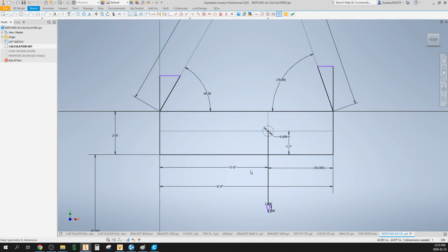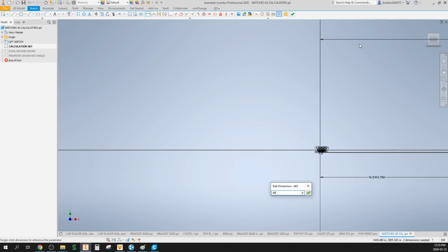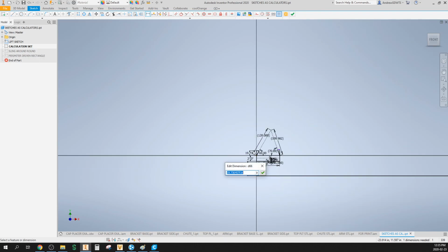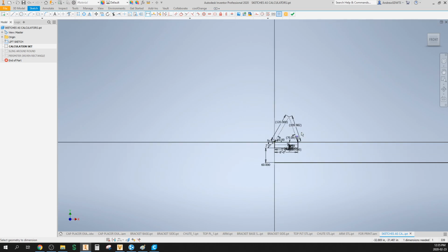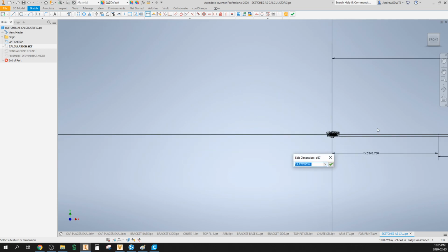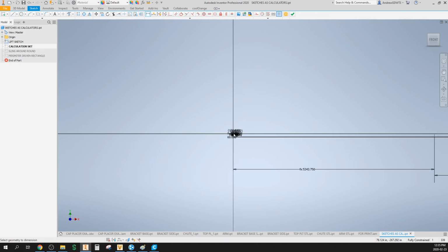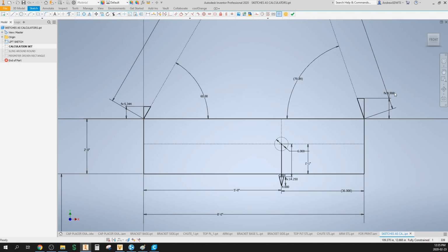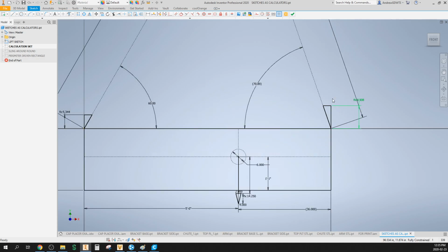To help me visualize this, I'll throw those weights into this diagram, but to make it more manageable, I'll divide them all by 1,000 pounds so that their scale is a little more reasonable. I'll do that for this last one. And there we go. Now we have a representation of how much more load this sling is picking up because it's closer to the center of gravity. That all makes sense, and that's pretty slick.